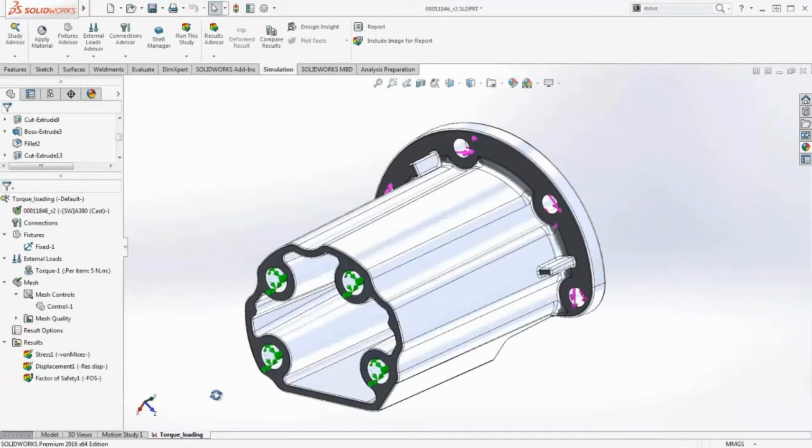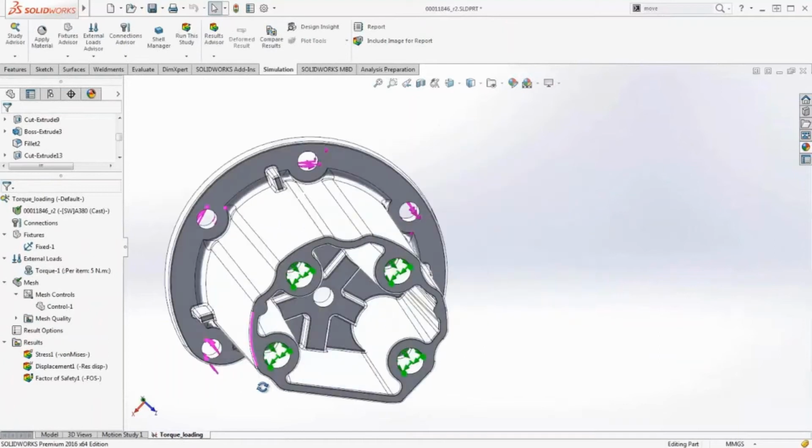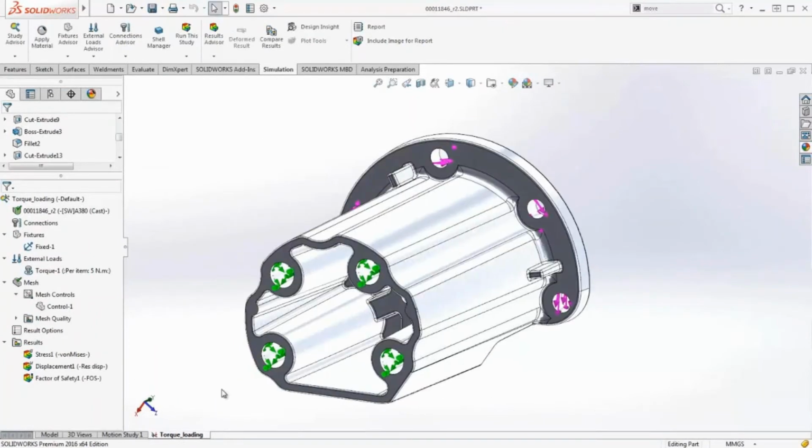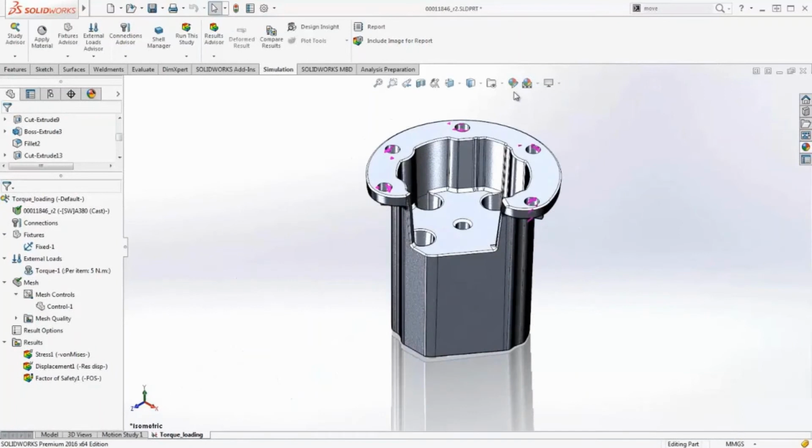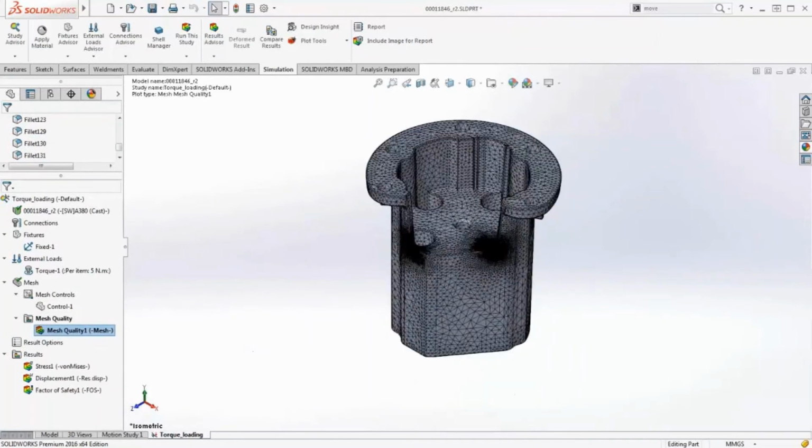loads. If you're wondering where this one has come from, it's from the robot Baxter, the red robot that you may see on all the 2016 information. This is one of the sections from it. Now it's important that we have accurate stresses, of course, which means ensuring that there's a sufficient detail level in high stress areas, such as any cutout regions.